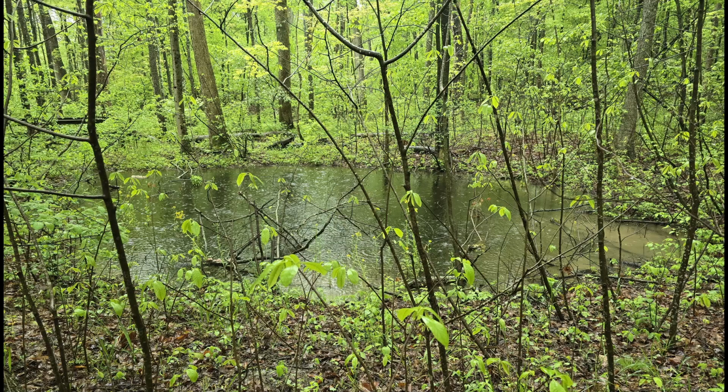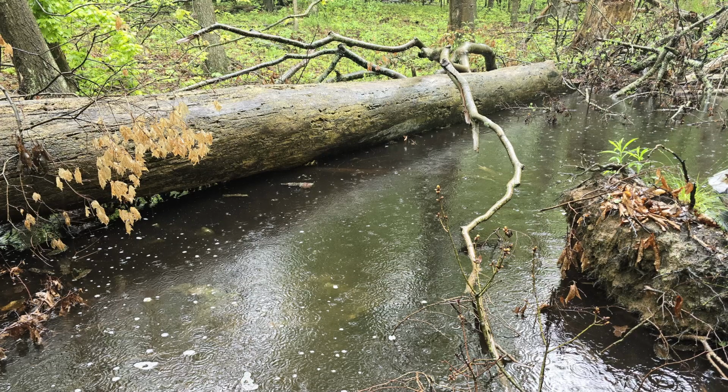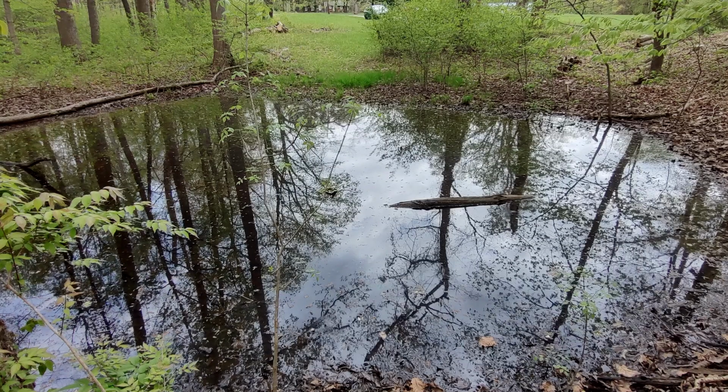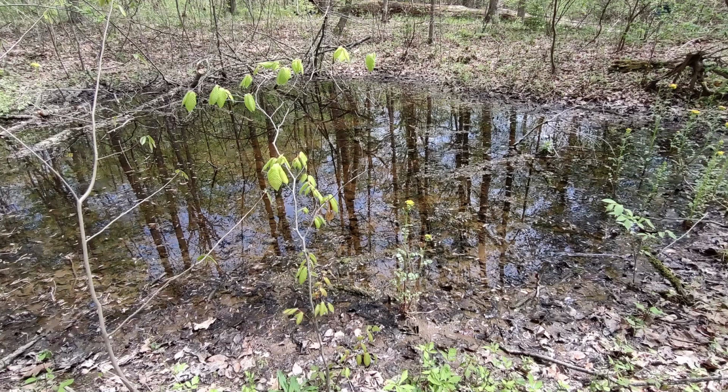This pond was built by hand over 2,000 years ago. It's located at Fort Ancient Earthworks and Nature Preserve near Oregonia, Ohio. Here's another one of the 114 ponds that were built by hand at the Fort Ancient Earthworks and Nature Preserve over 2,000 years ago. These ponds were built by excavating a basin by hand and then compacting the clay texture soil in layers. These wetlands have lasted over 2,000 years because they were constructed without dams, without pipes, or without water control structures, all of which require maintenance.